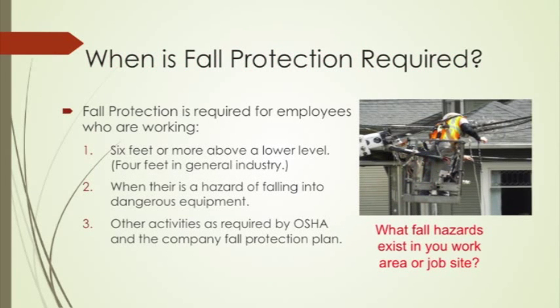OSHA requires that fall protection be in place on construction job sites when working at heights 6 feet or more above a lower level. If you are in the general industry, you must comply with the same rules when working at heights of 4 feet or more. Some regions require fall protection at heights lower than 6 feet, so be sure to check with your governing board.